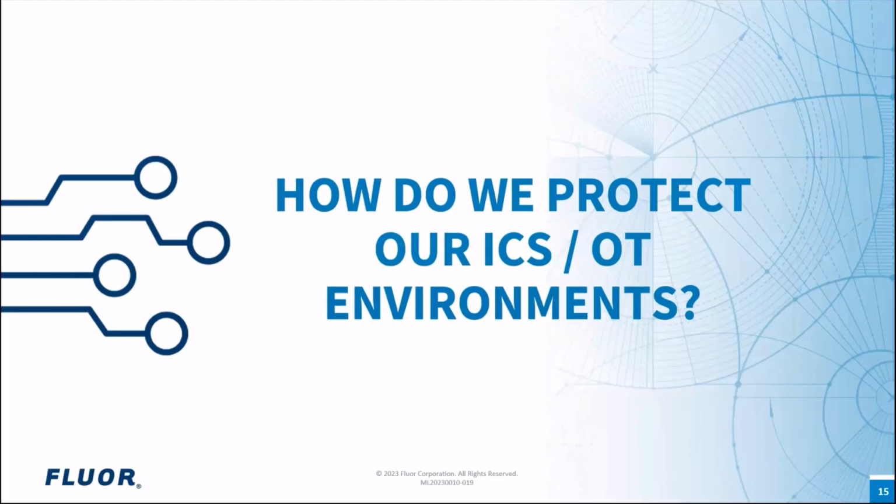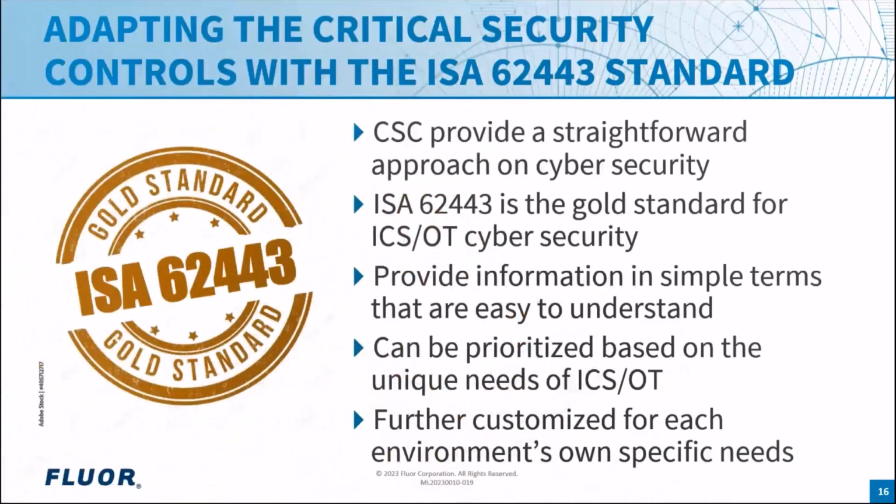So the critical security controls is an incredible resource for securing IT environments, but it's not specific to OT environments. Now, in the OT world, in the control systems world, we have the ISA 62443 standard. And like Ben mentioned earlier, there's a ton of different standards and frameworks you can use for securing IT environments. In the control systems world, we really look to just ISA 62443, right, which gives us a very detailed resource for protecting these OT environments.